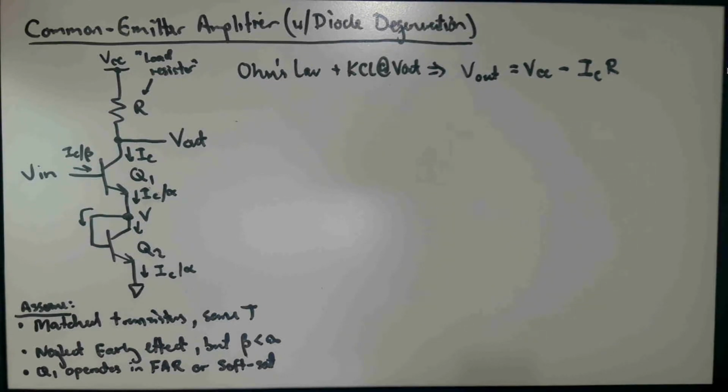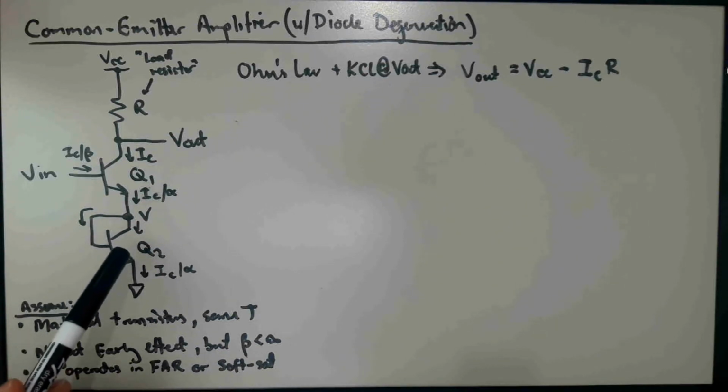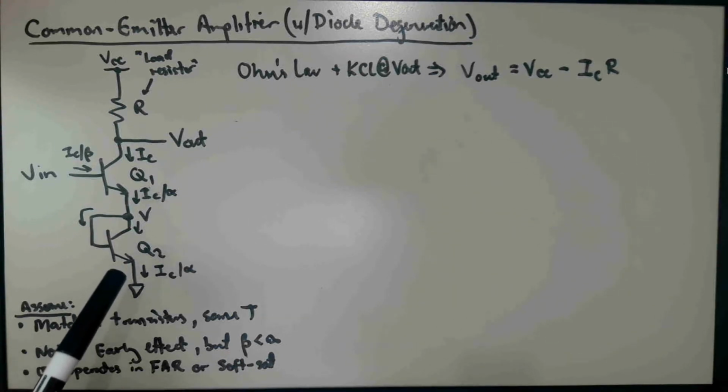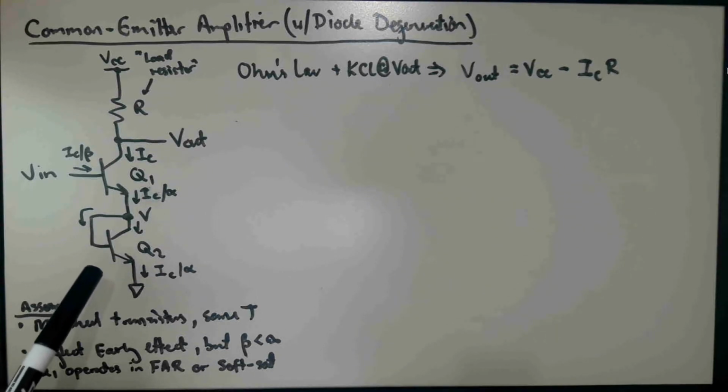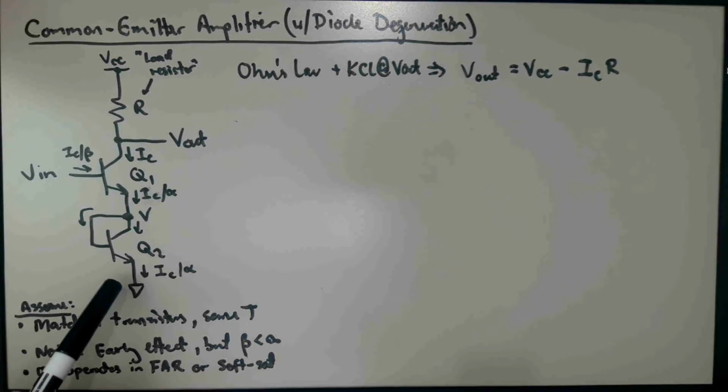Okay, so you should be able to convince yourself of that, because in the forward active mode, the collector voltage does not affect the collector current, right? It acts like a current source with respect to the collector voltage. And so the collector to emitter voltage actually doesn't matter with respect to changing the current. It's just the base emitter voltage.